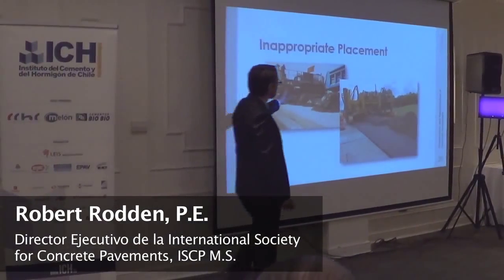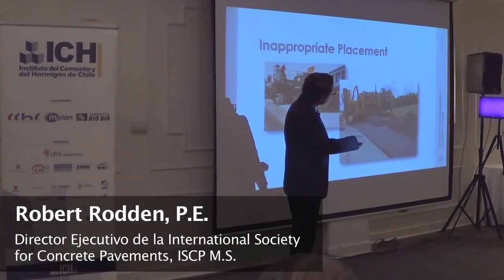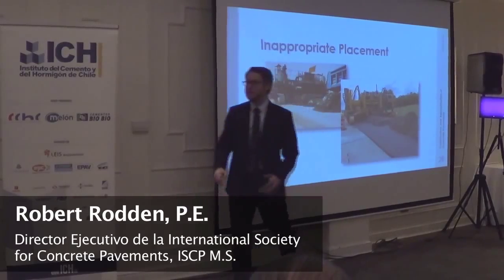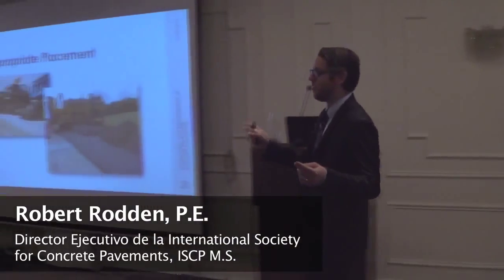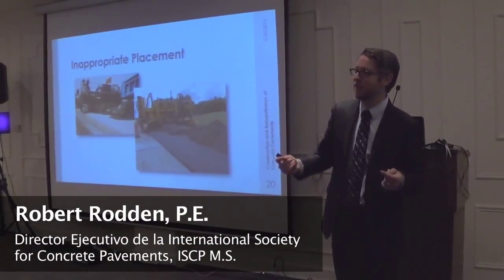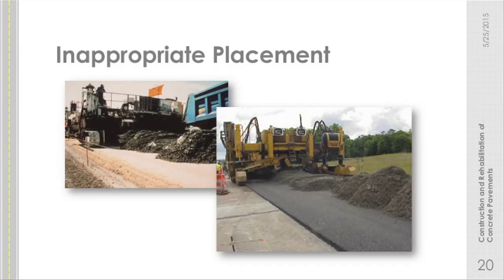This is improper placement. When we have these mounds of concrete, the paver has to somehow push that to the side, distribute it. Now, I understand the translator spoke to me during the break. We call this a head of concrete right in front of the paver. That does not translate well. It's just the supply of concrete to the paving equipment itself.